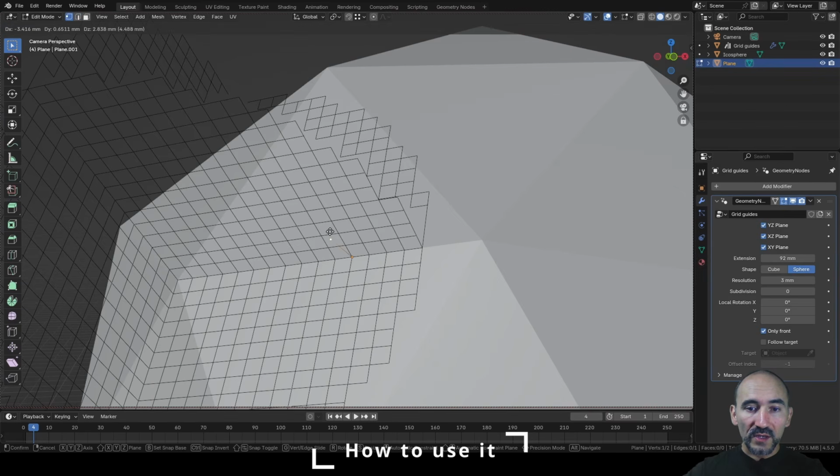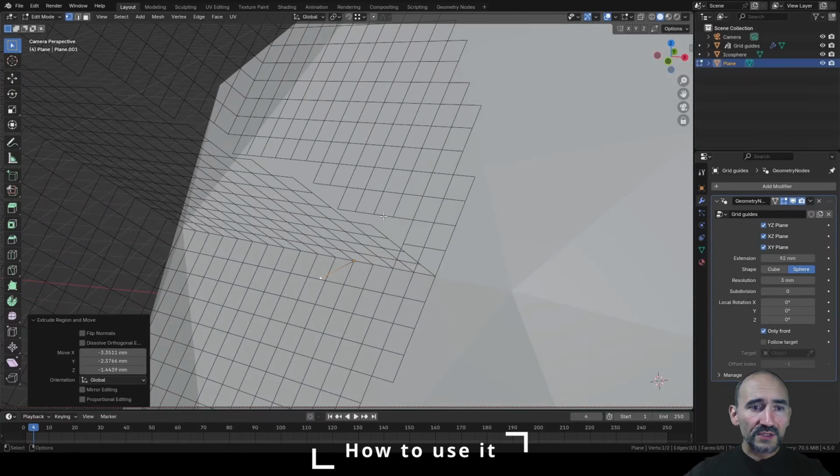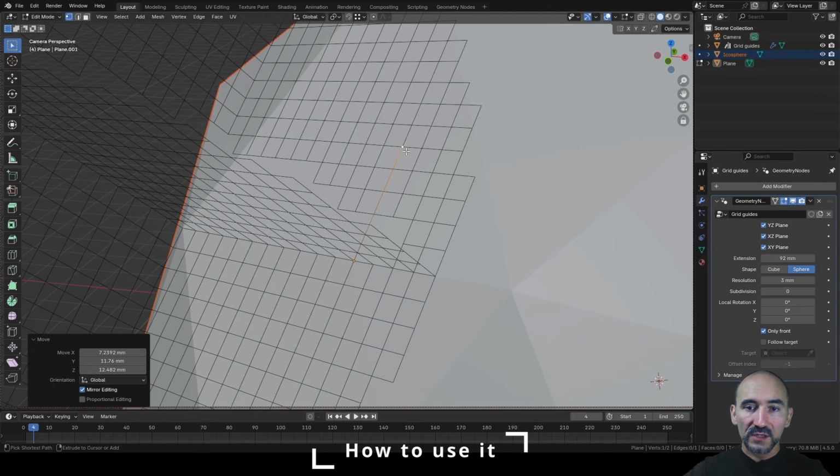this vertex, press E to extrude, and pressing the Control we can directly create a new geometry without using the rules, the measures, or manually entering the value on your keyboard, so selecting directly the final point for the extrusion. So in this case, I want to move these 5 units here.